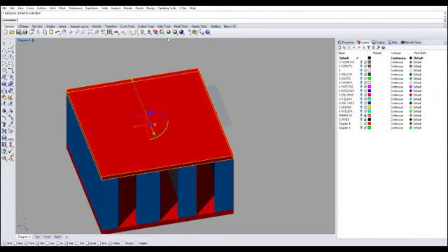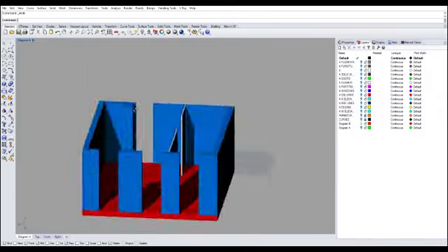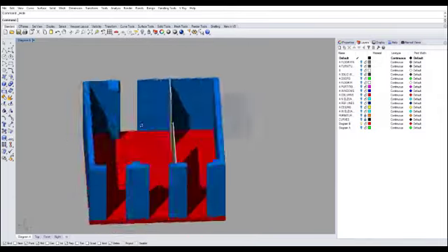I want you to find the light bulb icon. Do not click anything yet, just find it. Once you found it, there are also these triangle buttons below it showing that there are additional menus. For this particular run, I want you to use this button, which is called hide object, and it hides your ceiling temporarily for you, so that reveals the partition.